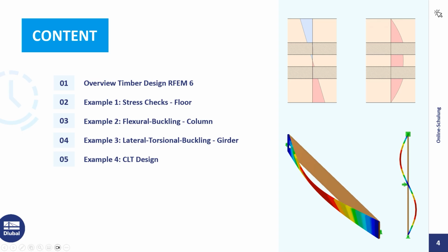You can see it on this image. You will see that the upper chord is failing in out-of-plane direction due to the high load. We need to consider this effect for girders, for example, for really slender beams normally.